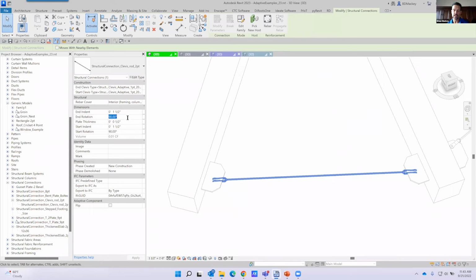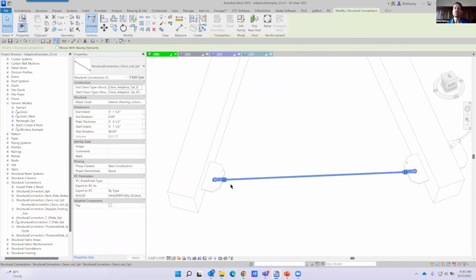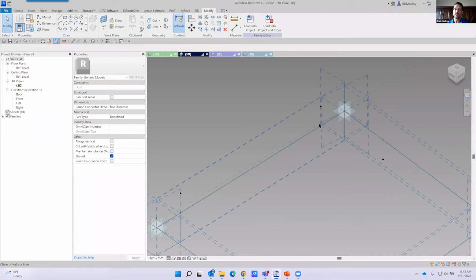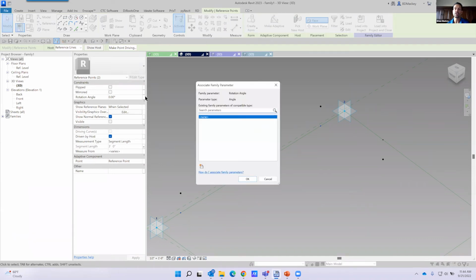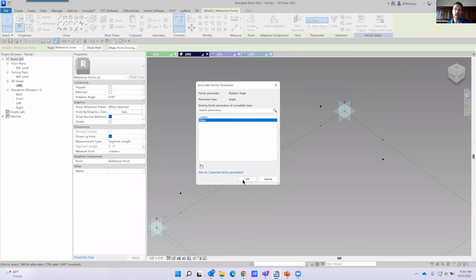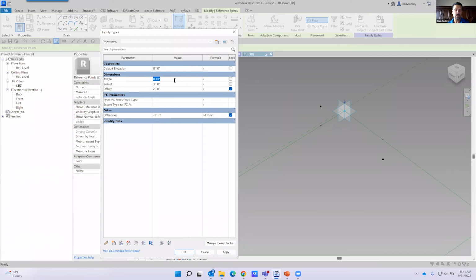Looks like I have them broken and they're both looking at the same value. Oops, that's a broken family. But what I'll do is I'll start adding rotations to those. And how that happens is simply by rotating that point. So if I needed these 2 points to be able to rotate out, I can select this one, I can select this one. And again, I can parameterize the rotation angle. So I can just call this my angle, whatever. Okay, and now I can start coming into my properties. And if I change that angle to be 15 degrees, say, okay, cool, make it a negative 15 degrees.